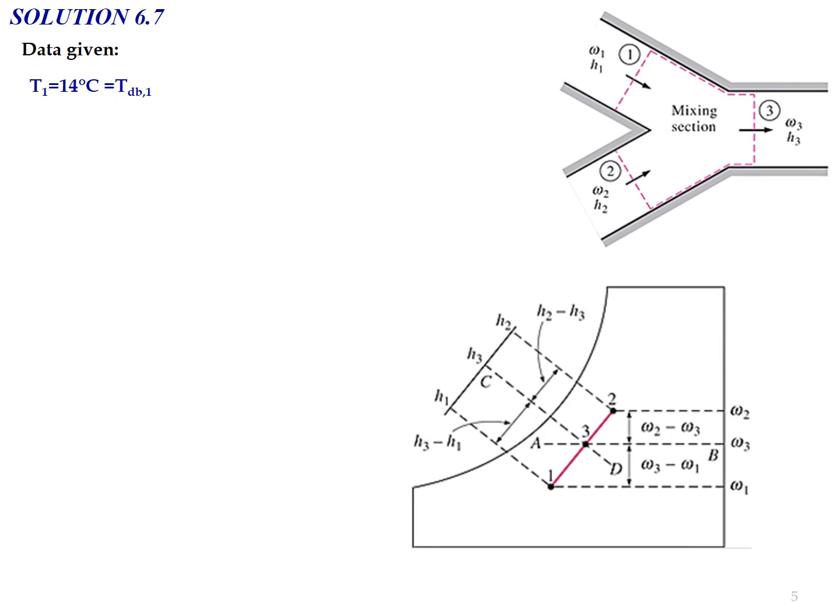In terms of data given, we have T1 equal to 14 degrees Celsius, the dry bulb temperature for state number 1, and psi 1, relative humidity, equal to 100% because the air at state number 1 is saturated air. Volume flow rate V1 dot equals 50 meter cubed per minute, and the pressure of the air is 1 atm, so we can use the psychrometric chart to determine the important parameters or values.